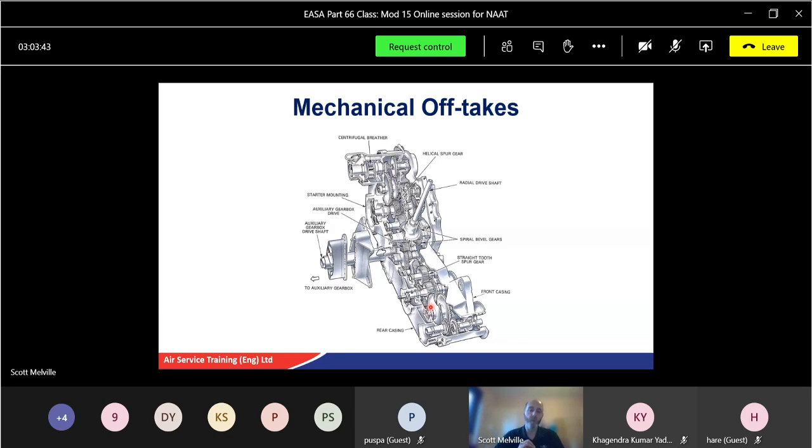The arrangement of gearing will determine the RPM of the accessories relative to the engine speed. So some of the gears will be larger or smaller depending on how fast they are to rotate. And certainly if you've got an RPM gauge, a tachogenerator as we call it, this is proportional to engine speed. So your RPM gauge, your tachogenerator, is proportional to engine speed, and we'll look at that later on.